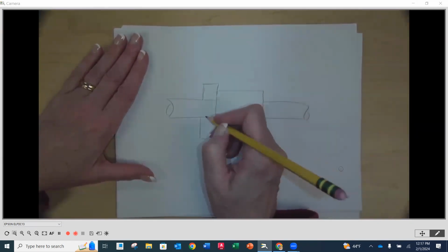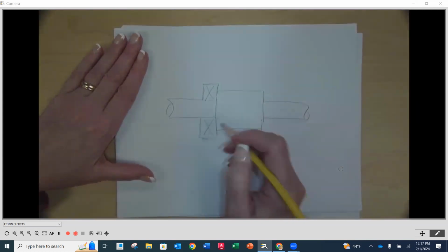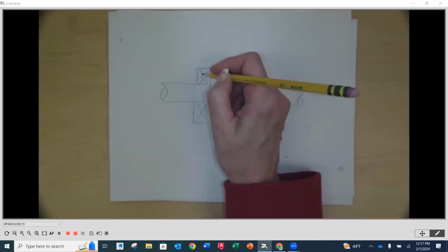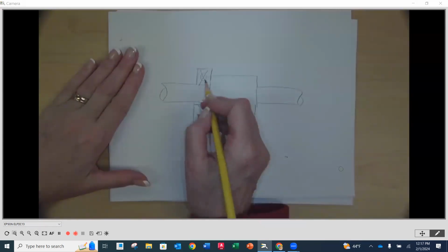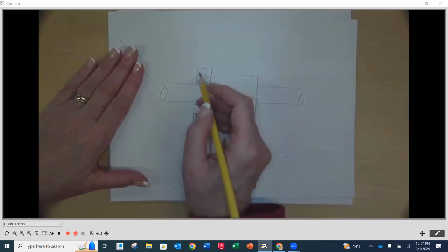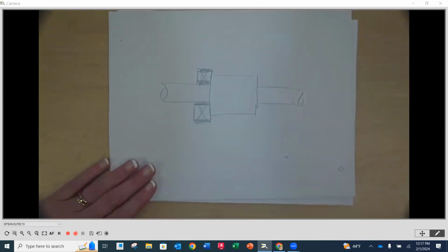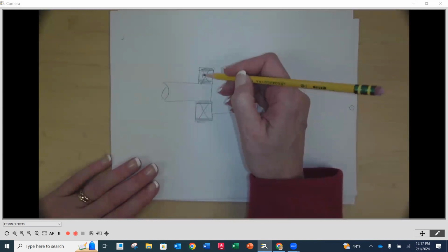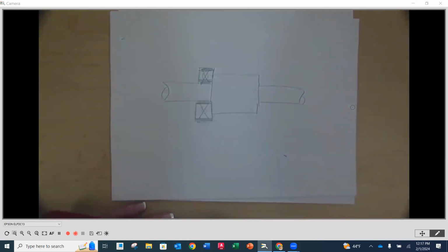That's okay. And then typically we just show this as a schematic. This would be where my rollers would be. My inner race would be in contact with the shaft. My outer race would be out here, probably pressed into a housing. And then it would be free to move by those ball bearings that are on the inside.